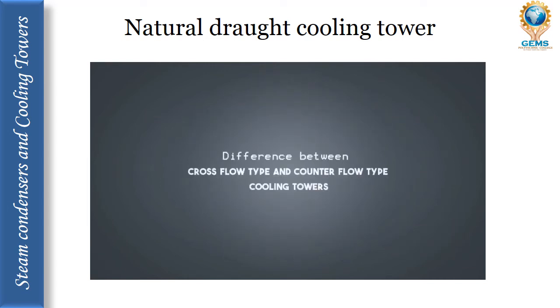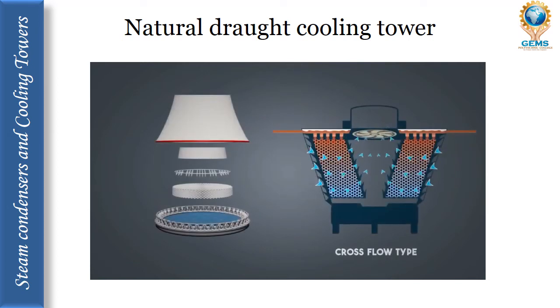Difference between cross-flow type and counterflow type cooling towers. The discussion will remain incomplete until we discuss the difference between these two types of cooling tower. In cross-flow type cooling tower, airflow is directed perpendicular to the water flow, whereas in counterflow type cooling tower, airflow is directly opposite of the water flow.